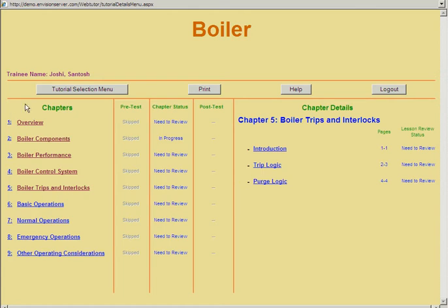Having explained the boiler process and the controls and interlocks, it's time to talk about operations in terms of pre-startup, how to start up, shut down, and post-shutdown operations. Then we cover some normal operations and cause and effect. We talk about some emergency or troubleshooting related issues: low steam drum level, rupture of heating tubes, flame out of all burners, and some other operating considerations like flame color. What does the flame color indicate? If there's a leakage in the tube or soot deposits, how do you handle that? Especially in oil-fired boilers. If there are measurement errors, how could they affect the boiler controls?